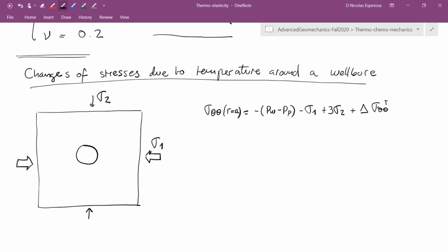And here, for theta, if this is the center of the wellbore, and this line aligns with the direction of the largest principal stress, then if I have an element somewhere around the wellbore here, theta is going to be the angle to that element from the direction of the maximum principal stress, and R is going to be, let me do it with another color.